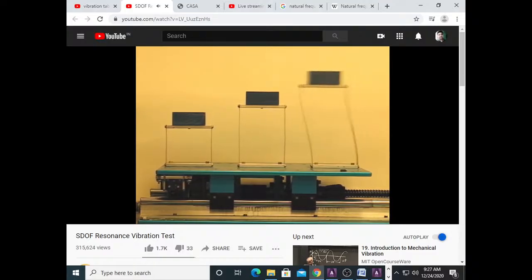This video will be very interesting to you. Okay, see, again they are now increasing the table speed. Now the third system has calmed down and the second system starts to vibrate, because now the second system's natural frequency matches the table frequency.